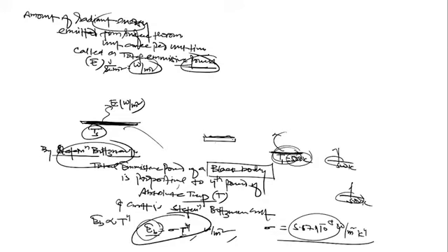So the Stefan-Boltzmann law has given the upper limit of energy that can be emitted from a surface at the given temperature. Nobody can emit more radiant energy than this idealized body, the black body, at any given temperature T. So if two bodies are there, one a black body and the other a real body, both at the same temperature, which body will emit the maximum emissive power?